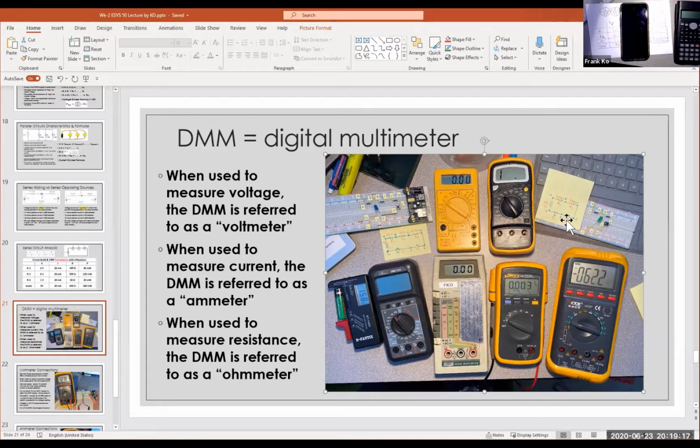Get the 100 ohm resistor pack, the 330 ohm resistor pack, and your jumper wires ready to build. You're also going to need the switch from your kit. For those of you who don't have the exact kit, in place of a switch, you can use a jumper wire. Okay, that's the end of our 5 minutes. If you ain't back by now, too bad.